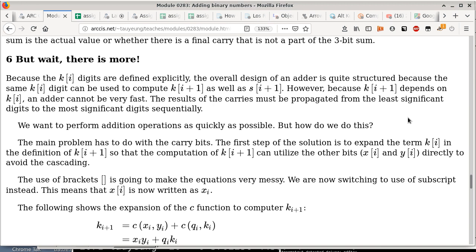So right now, because last time, we talked about a carry ripple adder. Do you guys still remember from Tuesday? Okay, I sent you guys the circuit diagram, or the Logisim file, so you can actually look into that and understand exactly what a carry ripple adder is and how it is constructed. But the bottom line of that, or the disadvantage of that, has to do with c_{i+1} depending on c_i. So, for instance, the carry of bit 5 depends on the carry of bit 4. The carry of bit 4 depends on the carry of bit 3, and so on.